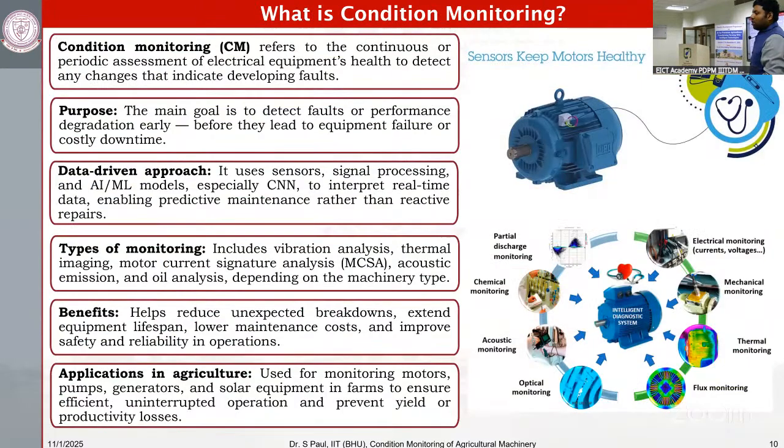So here comes the concept of condition monitoring. That actually comes under the umbrella of predictive maintenance. So what is condition monitoring? Condition monitoring refers to the periodic assessment of any electrical equipment. I will not go much deeper into what maintenance studies we do, but generally that study is done with the help of AI techniques. That is easier to do. You put a sensor at your motor and see what the current profile or the power profile looks like. You need not be an electrical engineer for that.